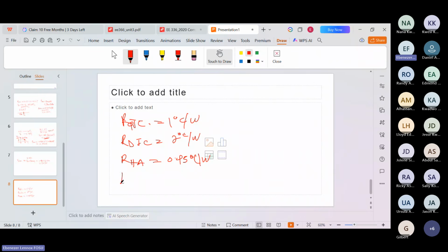We've also been told that E on is given as 0.04 millijoules and E off is given by 0.06 millijoules. We are asked to neglect the switching loss of the diode. And the switching frequency, that is Fs, is given as 25 kilohertz.